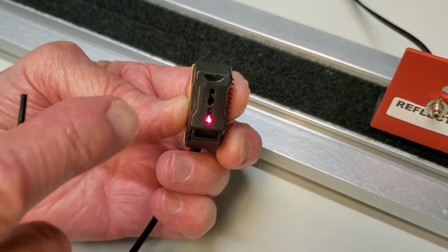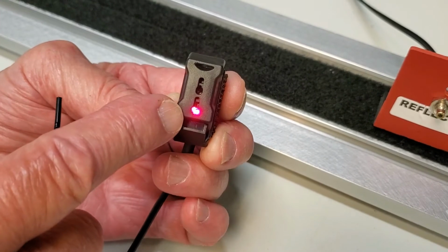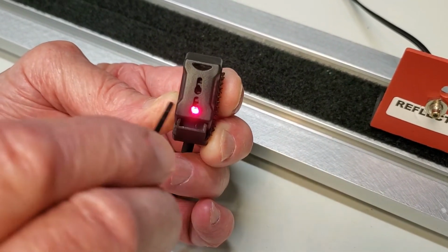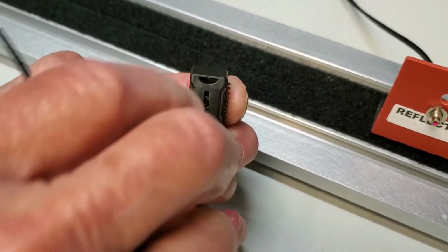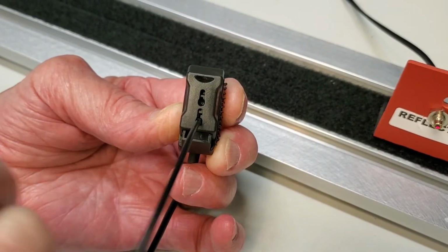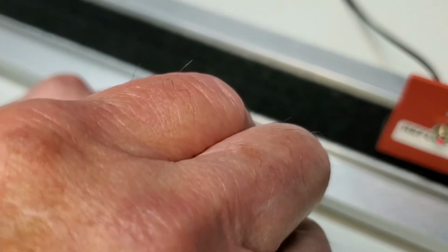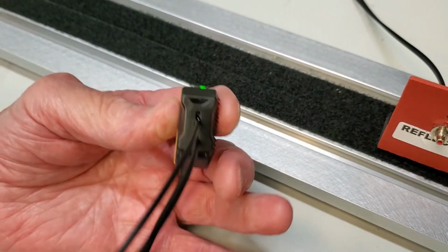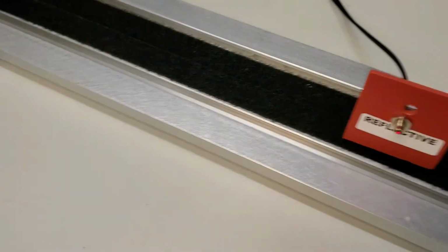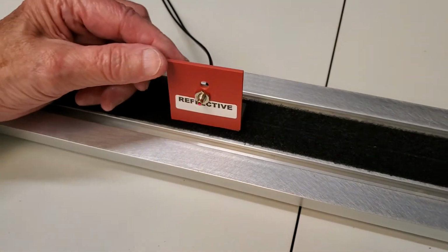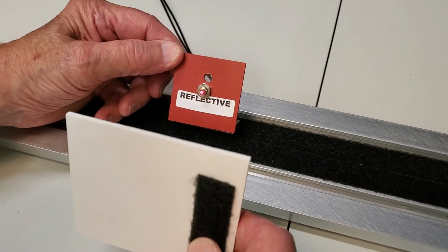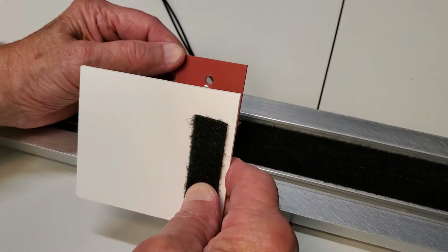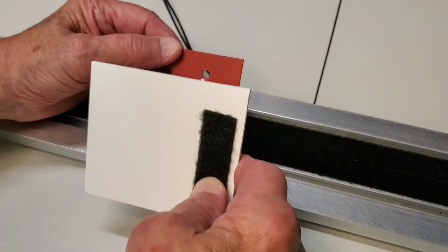Now, as you can see, the intensifier has been powered up and there's an infrared signal being sent out. We will connect one of the reflective cables into that sender and one to the receiver, and then we'll lock the cables in place. Now that they're locked in place, we're able to show that we can detect an item that is coming into the field of the reflective sensor.